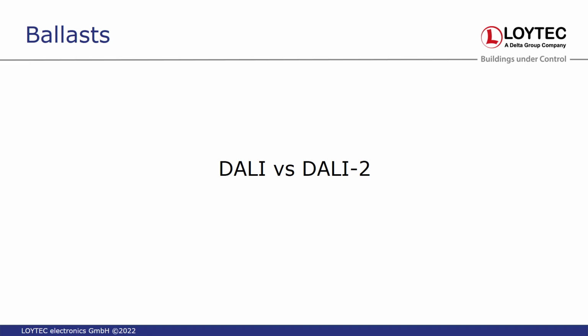Because what we have sometimes seen on some sites is that there are ballasts out there with some buggy firmware that are confused when on the same channel suddenly DALI 2 frames are upcoming, and when you have a certain content of the frame, they are getting confused and start acting in a strange way, or resetting or locking up or whatever.